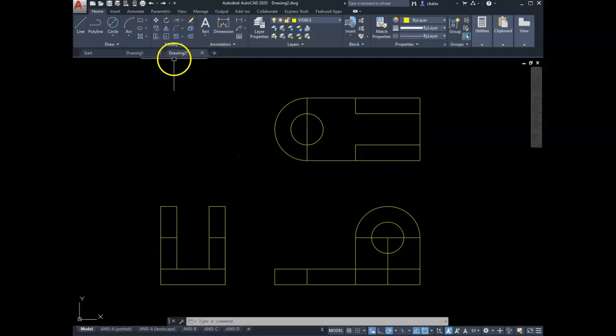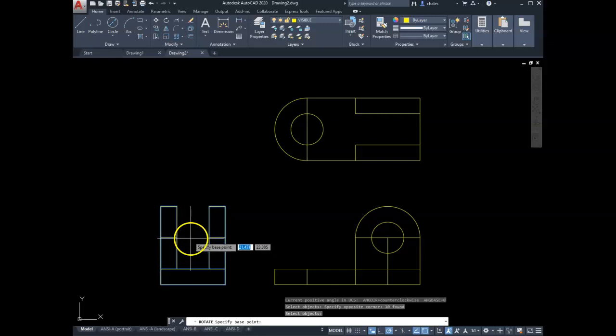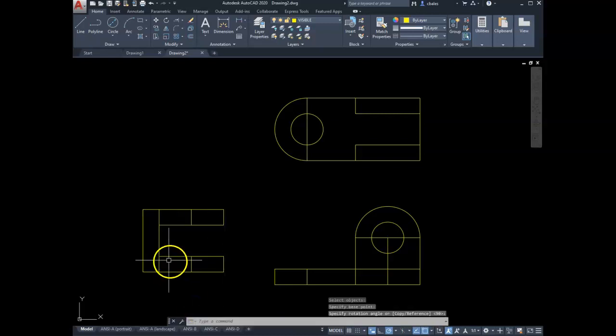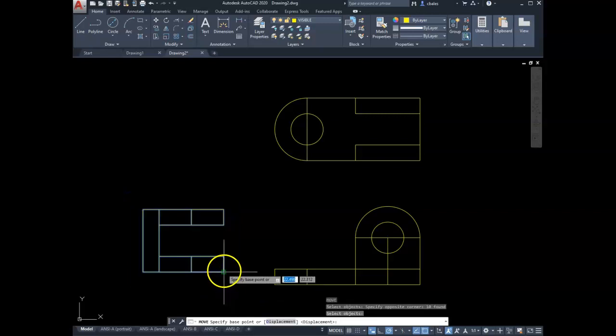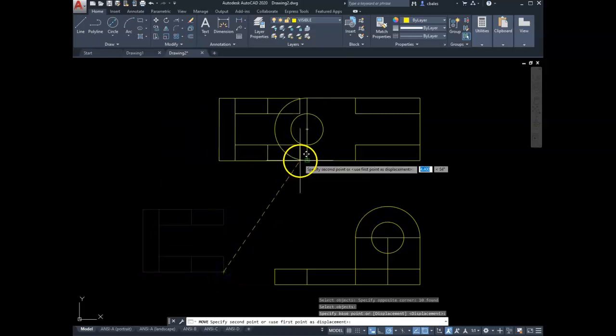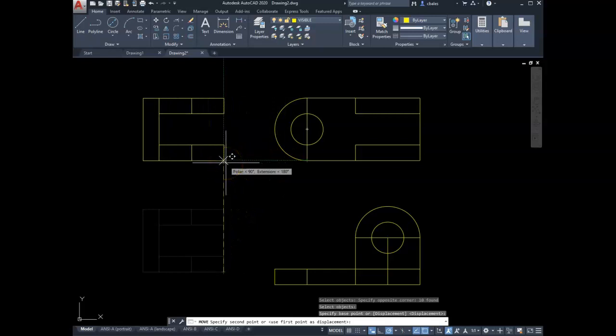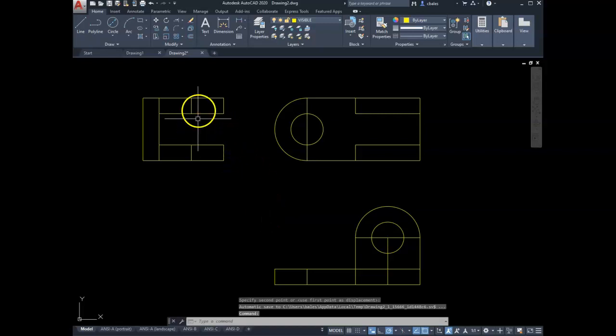First, we can use the rotate command, which is, where's rotate? There it is right there, rotate. So first we need to rotate this in the right direction. I'm going to rotate it 90 degrees clockwise. And now I have to move it into location. Again, here's where that little snap extension trick really plays a significant role. We can window those and select that. Now, I'm going to grab this corner here, and I want that to align right here. I'm not clicking, I'm just going to track it off, and where that stops right about there, there we go. All right, so now it's aligned.